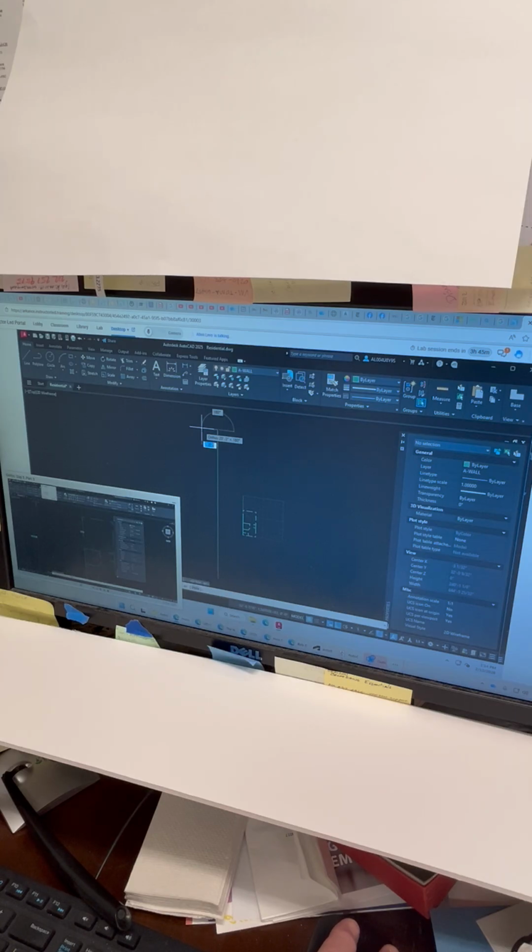And then there's some other information there about your current drawing, the scale and UCS icon and so forth. Look at that UCS icon. Is it on? No. Now here's the other thing that I didn't mention about the properties palette. It's interactive. If I click right here where it says UCS icon on and it says no, I can say yes. And there, now it's turned on. You know what I just did there? I did the same exact thing as turning it on over here.